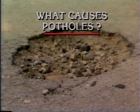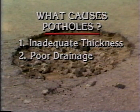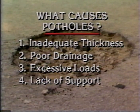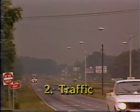Potholes can be caused by 1. Inadequate structural thickness, 2. Poor drainage, 3. Overstressing the pavement with excessive loads, 4. Lack of subgrade or base support, 5. Poor pavement construction. 2 factors must be present at the same time for potholes to form. These factors are number 1, water, and number 2, traffic.